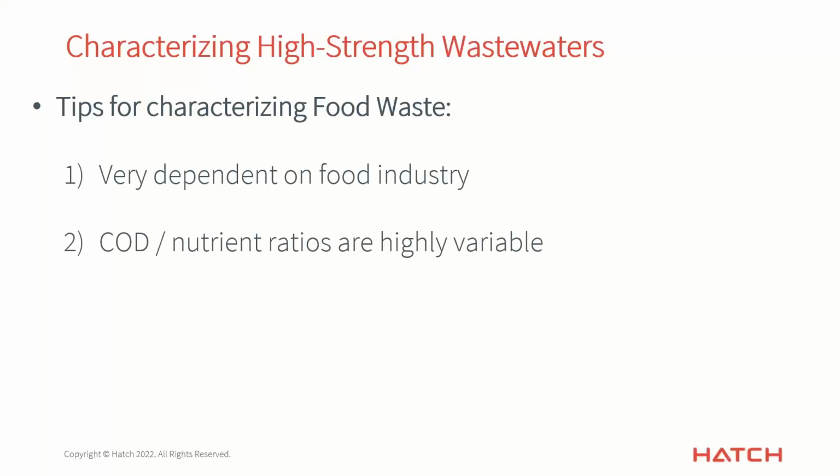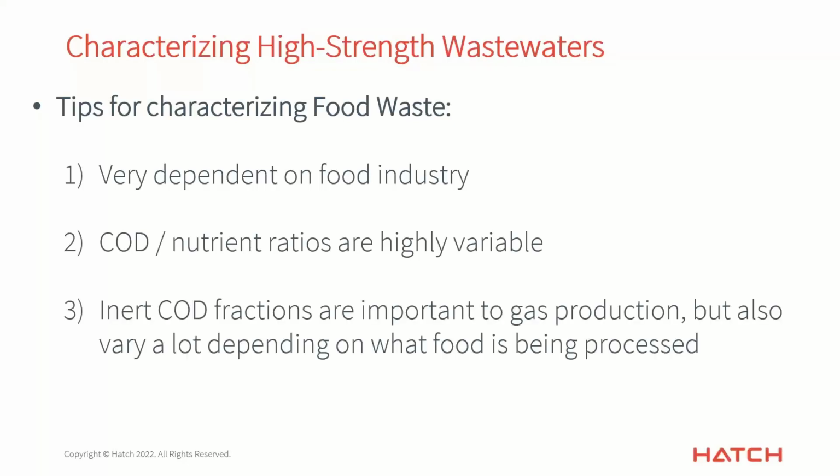And then I've also worked on other ones, like a rice processing facility where they had to add nutrients to the wastewater to allow it to be released into the sewer system so that it could go to the plant, because it was so low in nutrients, all COD, no nutrients at all practically. So you can have it all over the map.